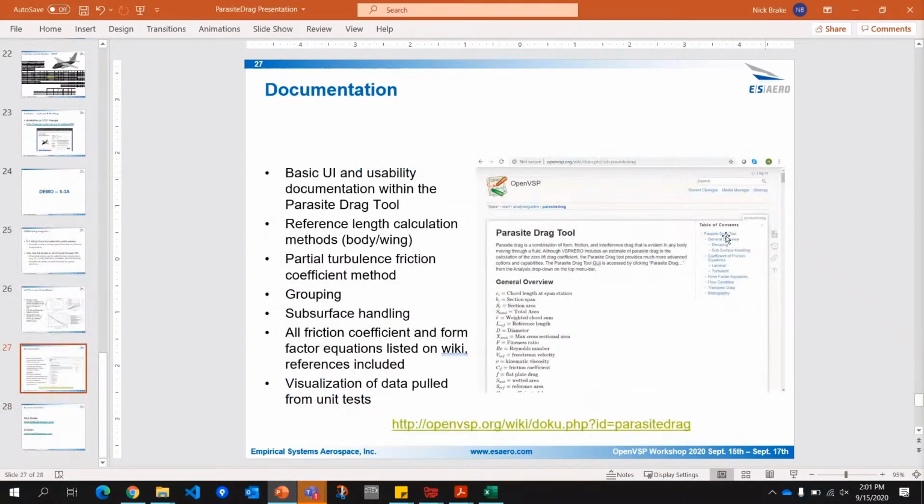For wings, and also for rotating propellers and rotors, it treats the wing in a stripwise manner, calculating the local velocity, the local Reynolds number, and applying a simple form factor, but it's essentially data based on an NACA 0012 out of Theory of Wing Sections.